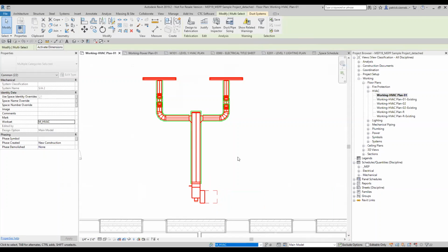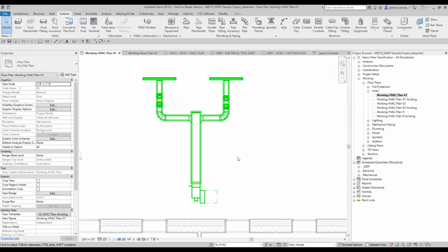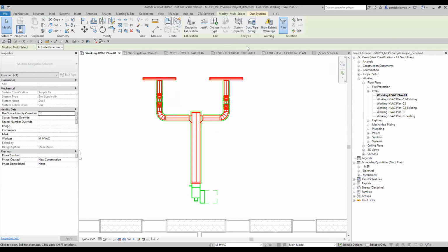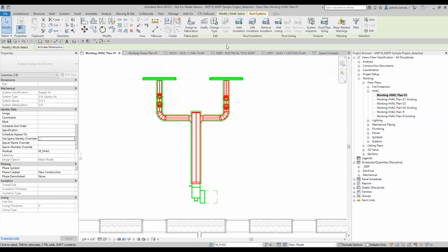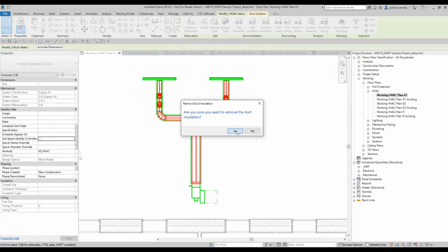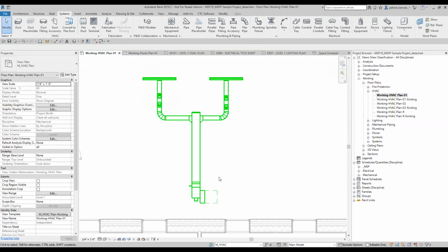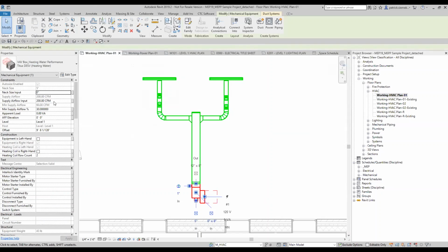So a lot of the great features I have here is the content that has been created. A lot of it is smart content. One of the examples that I am going to use over here is the change of your VAV units. So by selecting a VAV unit and looking into my properties here on the left, I could see that the unit, based off of the calculation that it is getting of the airflow from the air terminals, is driving a neck size value of 5.